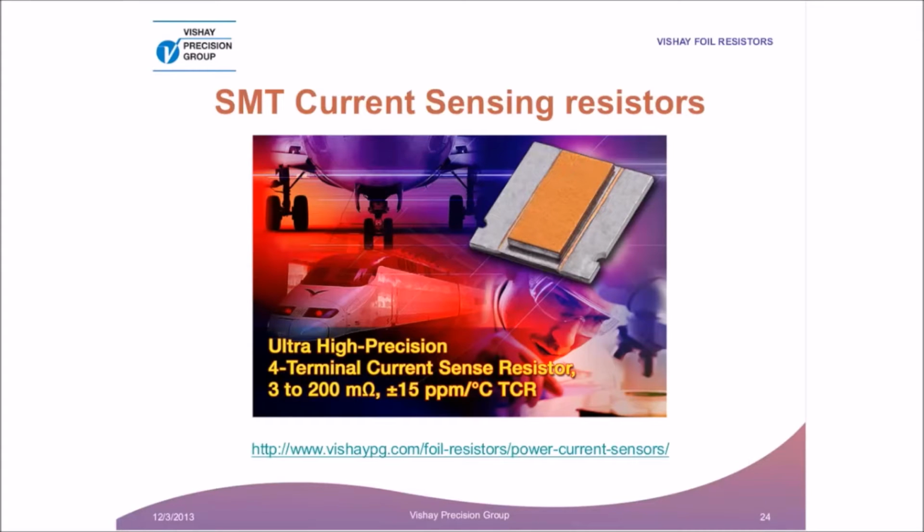That's a picture of the CSM3837P. That's one of my designs for an even higher power and more robust version of the CSM. It worked out very nicely. You see there is the heat sink on top of the resistor element. The foil current sense resistor is based on our expertise in stress analysis and proprietary methods of manufacturing 4-terminal resistors. Their use of Z-foil technology allows them to achieve very low TCR, PCR, and virtually no thermal EMF over a very wide temperature range. Next page.